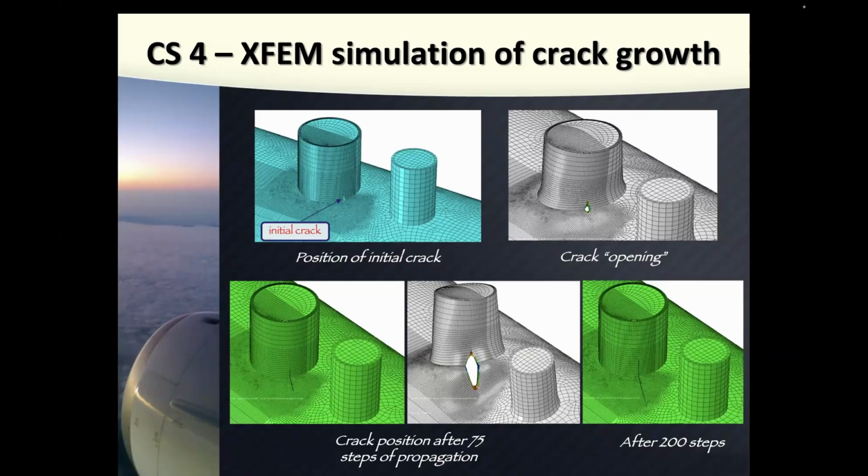Yes, it's mostly because of the plane stress condition. Let's not forget all the examples I showed you here are thin wall structures. That's your point. Also here, we stopped the calculation after 200 steps. I remember it took something like 2 days, because I made a very large number of nodes in this area. Nodes are not changing during crack growth, but with a very large number of nodes, there is a very large number of calculations.